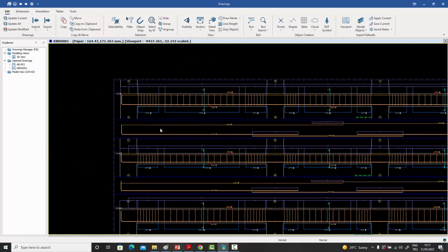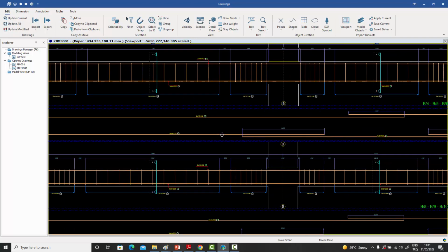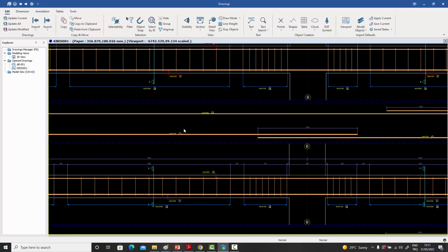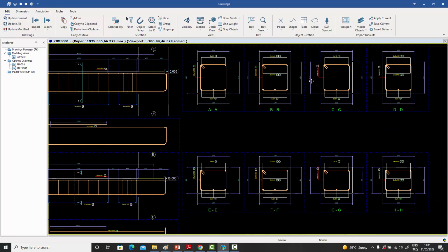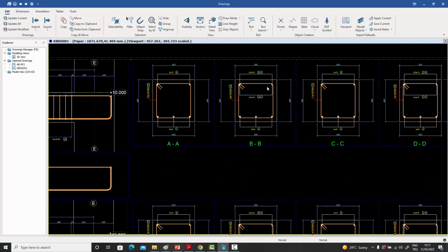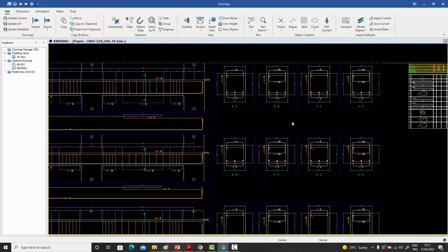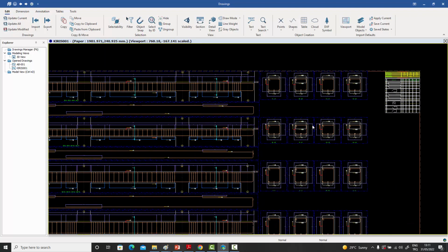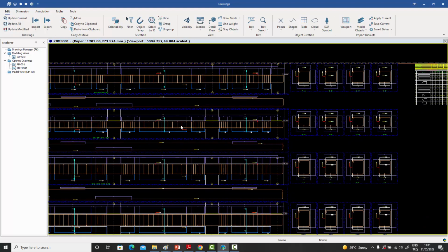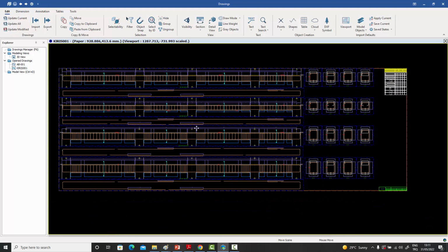The individual bars have been opened up below the beam, so you can see them and you can see the dimensions, and you can see the part marks very neatly. The sections have been taken. You have complete control over where the section will be taken, how the section will be, how many sections you want. Do you want a section everywhere there's some change, or do you want just one in the center? Those kinds of customizations are available.